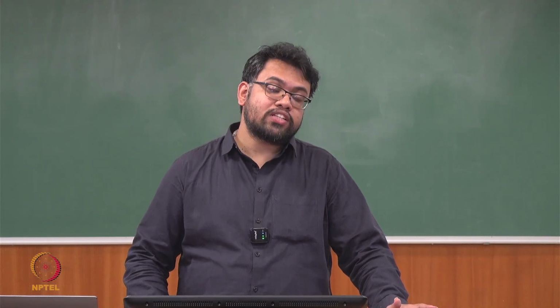Good morning, everyone. Today we will discuss one special topic of the 2 degree of freedom system, related to vibration control, because often the 2 degree of freedom system can be used for vibration control if we are thinking of a base isolated structure or a tuned mass damper. Both can be predominantly modeled as a 2 degree of freedom system. Here let's see how we can find the optimized parameters for a tuned mass damper or a base isolated structure.